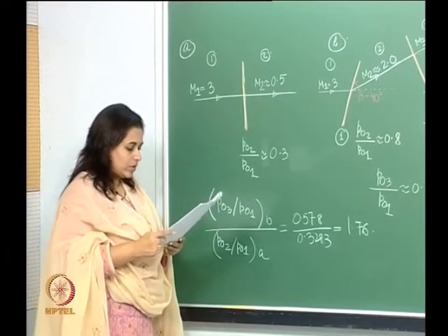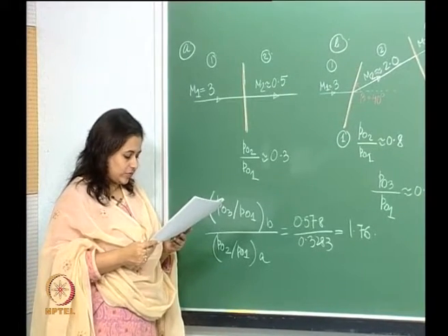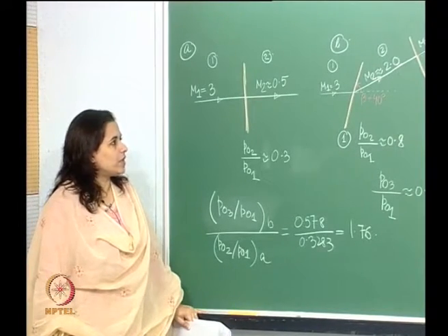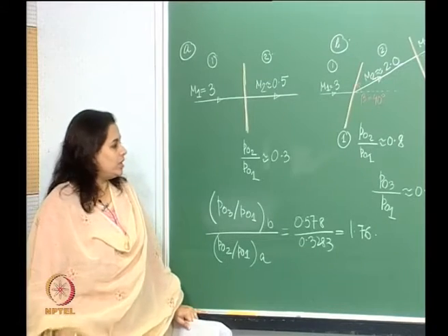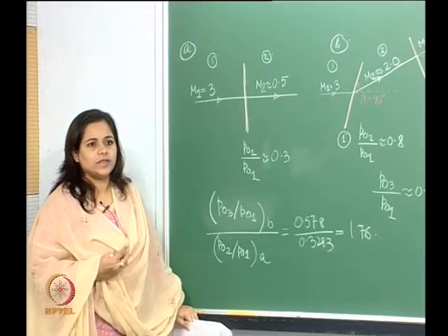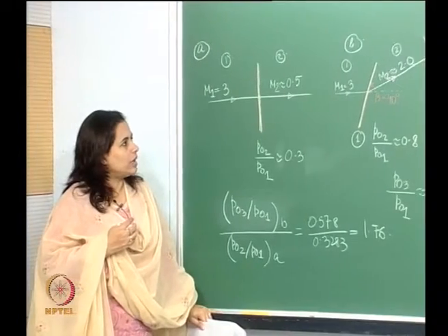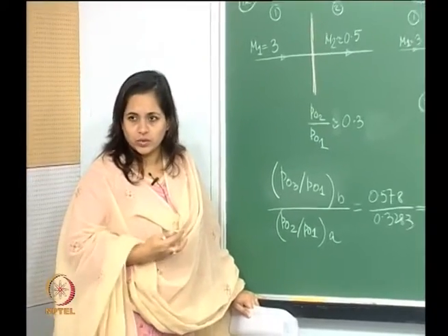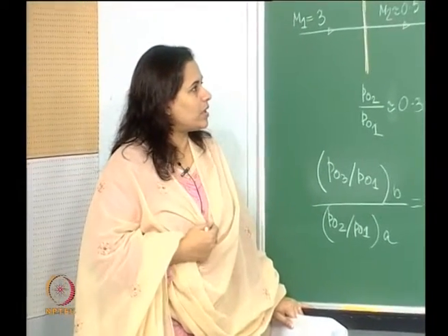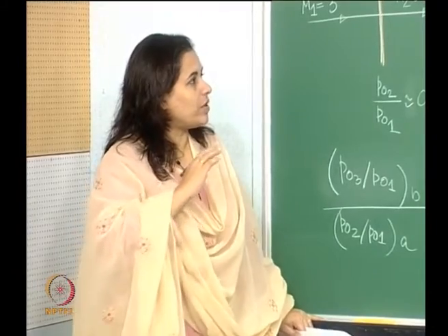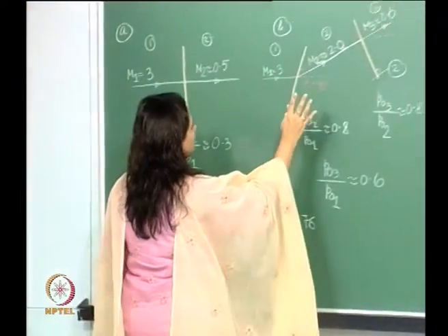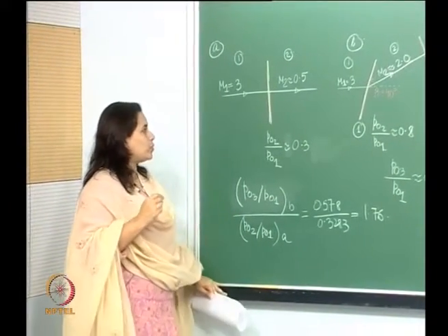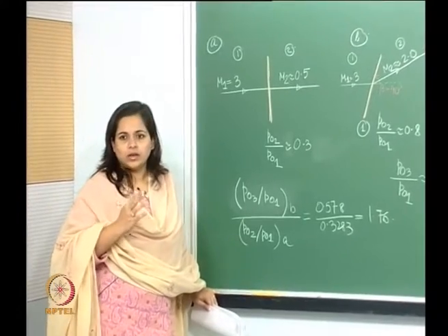Okay. Now, what does that mean? Well, this total pressure gives us an indication of the total useful work that this can do. And whether this is more efficient or this is more efficient is going to be decided depending on how much we are losing in terms of the total pressure.